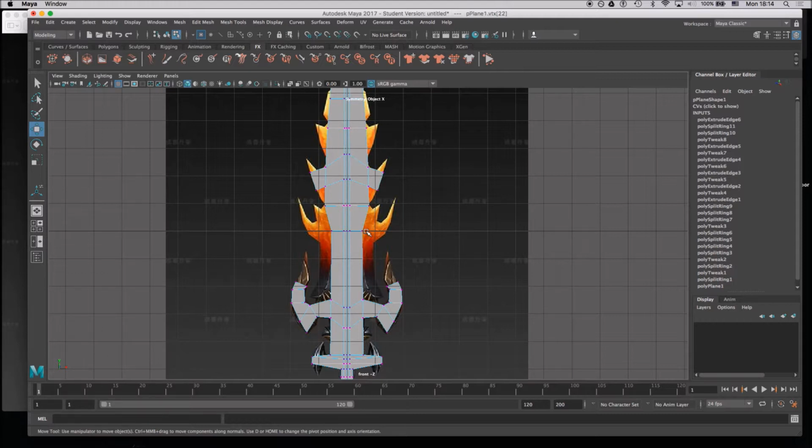Instead of adding edges, can we just add individual vertices? I'm looking at my volume here, right? And I want to add extra vertices here and here. Is there any way to do that, to add a whole edge loop? In general, you want to have each point or vertex touching quadrilateral shapes. And so it's not actually too big of a deal to add edge loops. If you do add an edge, you want to continue all the way around your model. It's not too bad to do that.